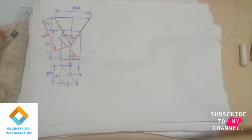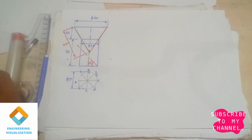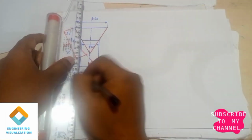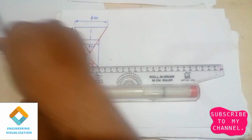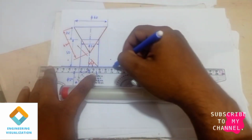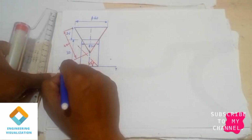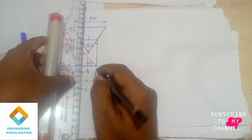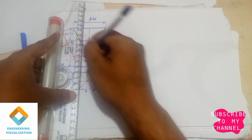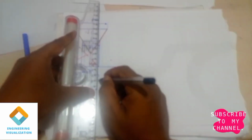Now we'll project it upward so that we can write the top and front view notations. Here I'll differentiate the top and front view with the XY line, so that we can clearly understand it. In this problem, guys, we are starting from the front view and then finishing with the top view. Usually we start from the top view, but in this problem we started from the front view. So draw the projection lines.